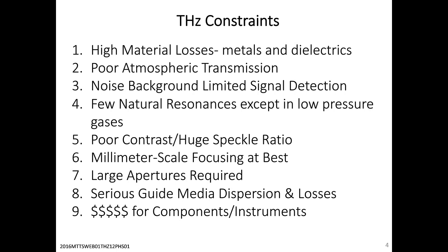So you have to be careful how you do imaging in this wavelength range. And again, we'll talk about that. A lot of people talk about terahertz being used for very high-resolution imaging, and you have to remember that when you're working with a wavelength scale of about 1 millimeter, your focused spot size is also going to be of the scale of 1 millimeter, and so you can't really do very high resolution imaging in this range.